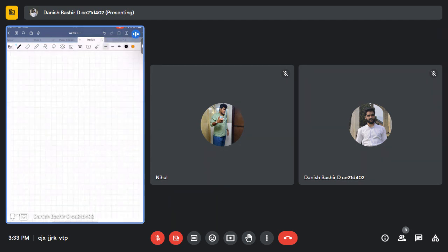So the total number of equations that we can write for a truss member, for a truss, I write it as ne. The number of equations is 2j for j number of joints plus 3 external equations. Okay, this is it.